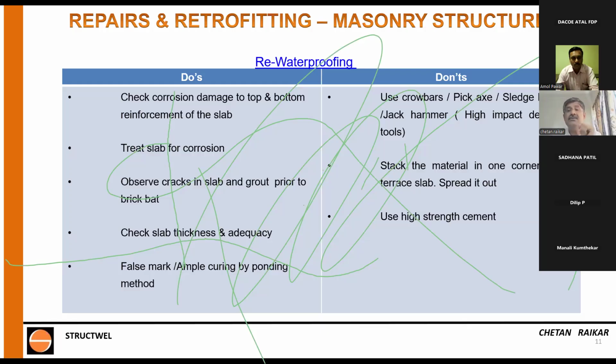See, why this is required is in an IPS, we sprinkle dry cement on the top, and that dry cement shrinks. If you want to contain the shrinking, you break the topmost portion of IPS, which is maybe 3, 4, 5 mm, into small square shapes of 300 by 300.